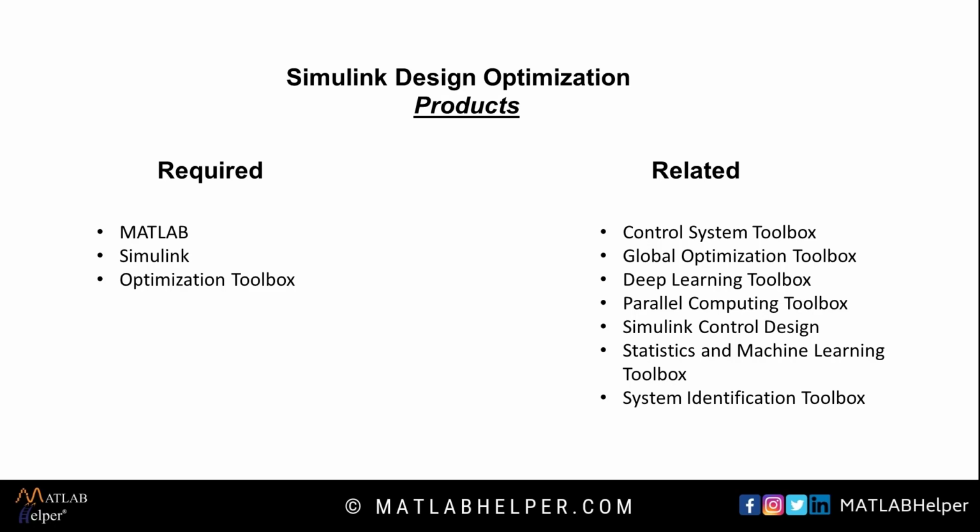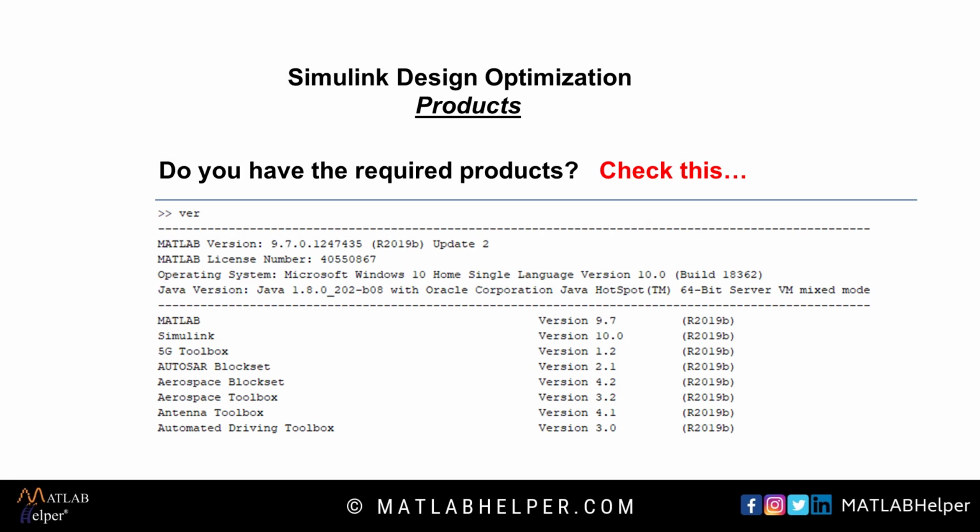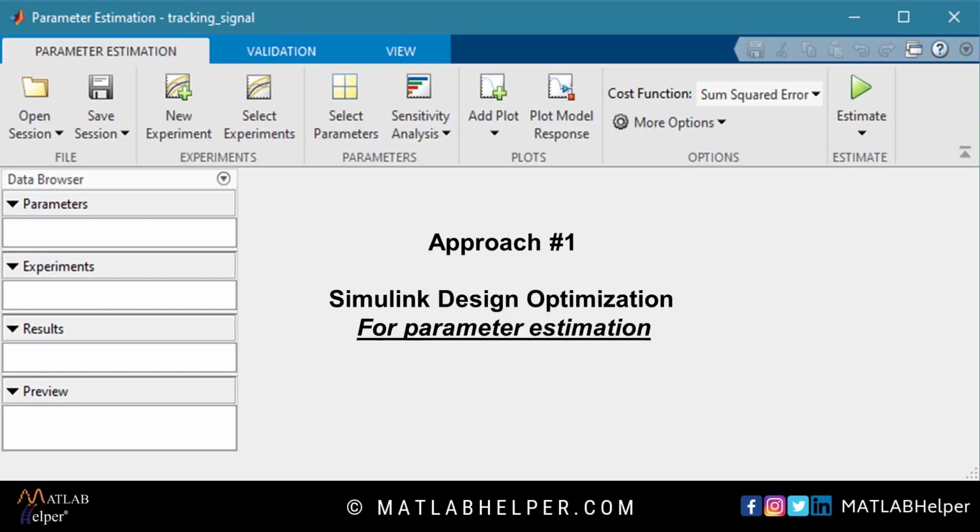In fact, most of them will provide you help for linearizing systems, tuning controller parameters, and some optimization techniques. By the way, you could find out if you have all of these toolboxes by typing VER in your command window. So now the approaches will be introduced.